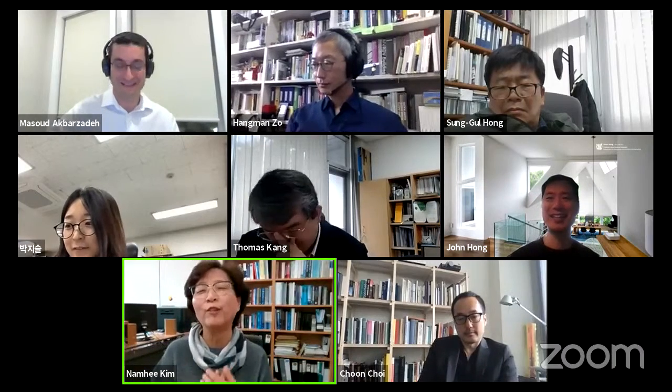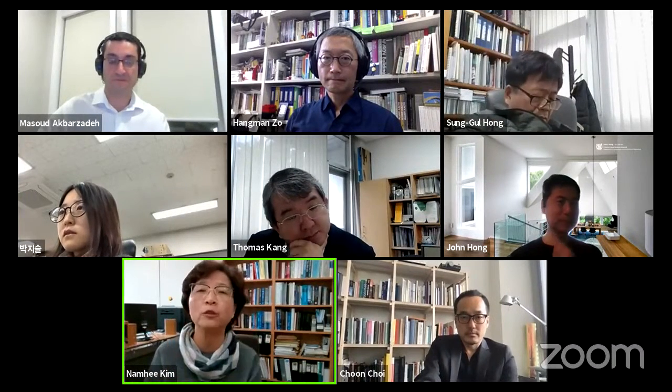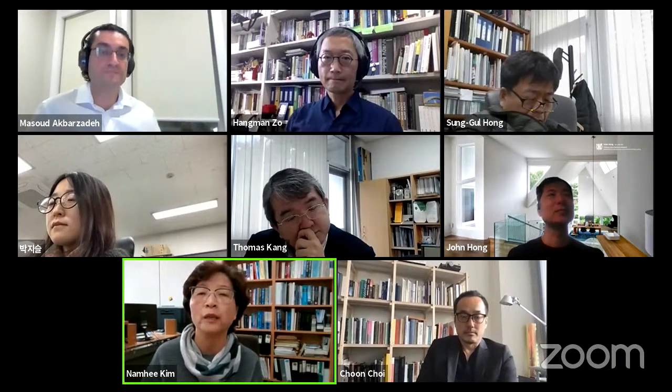I was very impressed by your presentation, but I'm still hungry for your specific knowledge to learn. Actually, I'd like to agree with you. The graphical approach is not dependent on the scale at all. That is totally independent of scale. Yes. It only depends on the ratio of dead load to live load, etc. But anyhow, to avoid unexpected loading cases or some member deformation, we have to provide somehow an alternative load path in terms of redundancy. Exactly. Would you do that?